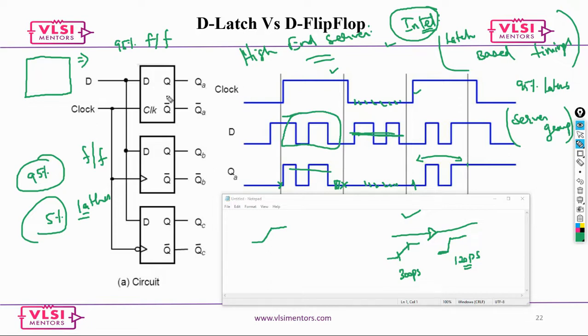That is what I'm saying. We will cover everything in a topic called static timing analysis. If you look at any kind of sequential elements, they all operate the moment the clock comes. So it is always going to be clock to Q delay. We always call it a clock to Q delay, whether it is a latch, a flip flop, or macros, say memory.